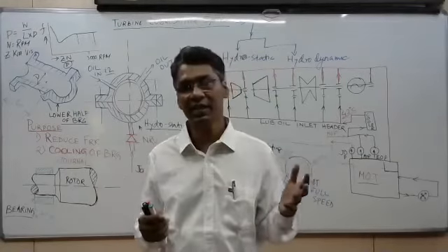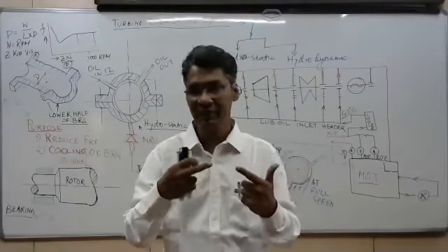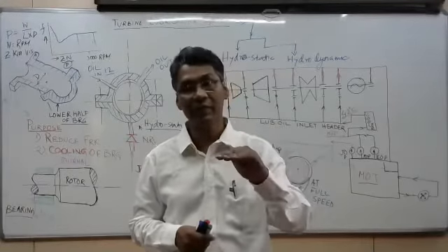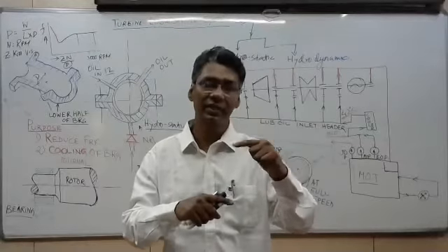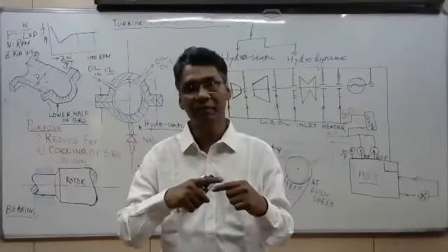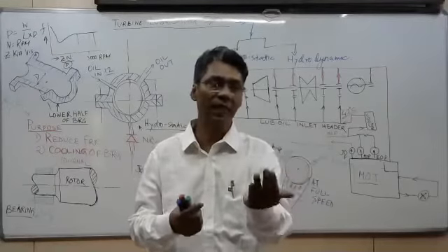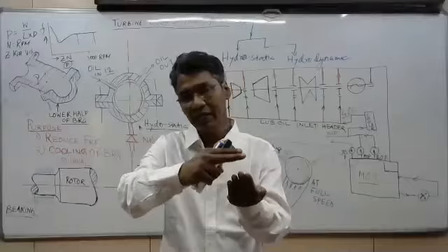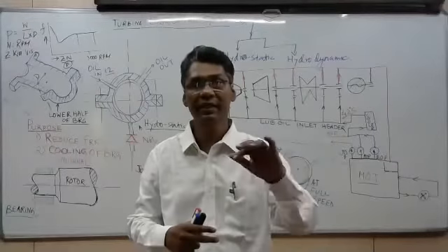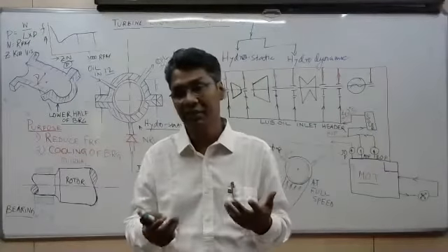But the difference is that the surface of the journal is very highly finished and the bearing is made of some alloy which is softer. That means it can be replaced. During maintenance, if there is any damage in the bearing part, we can change the bearing halves very easily. So we intentionally made it a lead-based alloy bearing surface so that it can be changed easily.